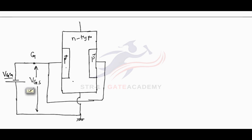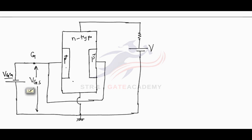And drain terminal is biased at higher potential with respect to source terminal. This battery VDD will be responsible for the current flow in the device. According to the terminal of battery, there will be an electric field in the channel in this direction. This field is basically responsible for the flow of charge carriers in the channel.